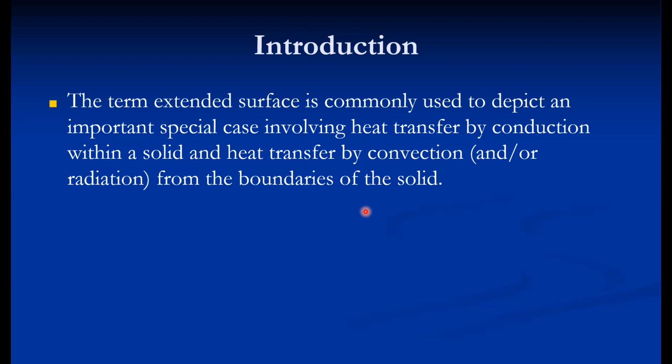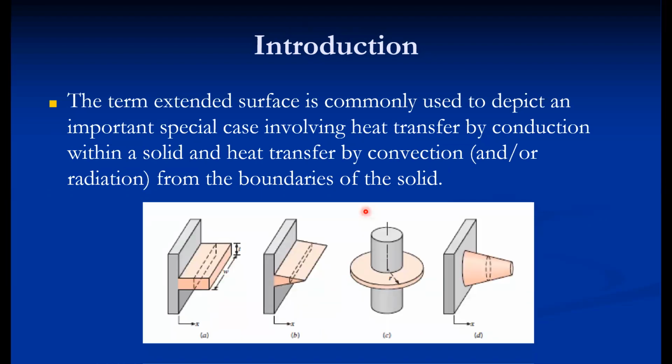These are the various extended surfaces used in practice, and according to their shapes, they are called a rectangle fin, a triangular fin, an annular fin, and a pin fin with non-uniform cross-section. There are different fins used, especially to enhance the rate of heat transfer from the surface. It is more efficient in natural convection; for forced convection, it gives a lesser efficiency.